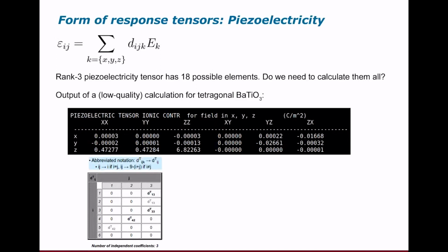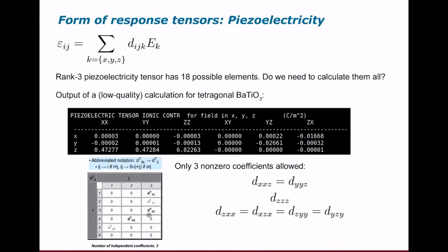For these rank 3 and higher rank tensors, the server uses something called the Voigt notation, where for the XX, YY, ZZ, YZ, XZ, XY components, you have 1, 2, 3, 4, 5, 6. So instead of a 3-index tensor, this uses a 2-index tensor, where the first index takes care of all the strain components, for which you typically use 2 numbers. But anyway, this takes a slight bit of getting used to. So we can spend 10 minutes on describing this, but I will not.